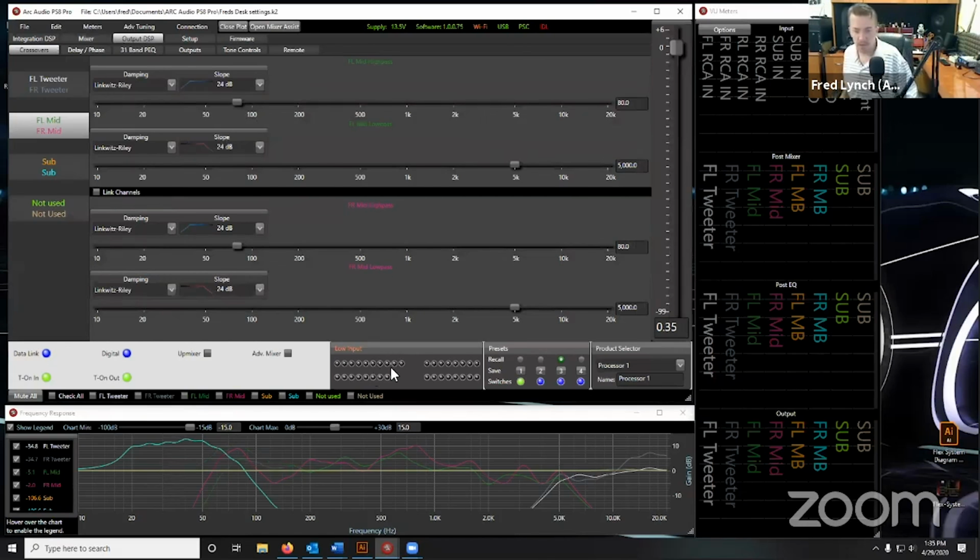Also down here, there have been questions in regards to this panel. It says low input right now. This is a meter input system. These are color-coded indicator lights: if you put full range pink noise into your source unit and follow the color indicators of those lights, they will change colors. The indicator on the top, or the text box in that top bar, will tell you if you have good signal or low signal.